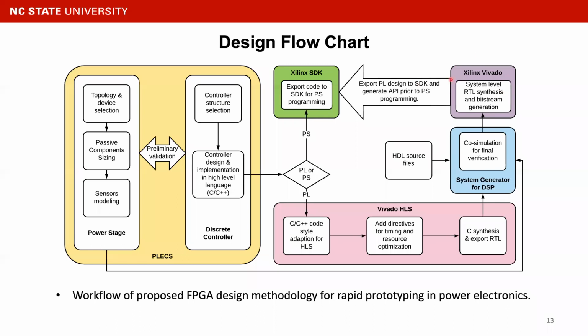After the bitstream generation, this concludes the development for the PL side. Then once the PL design is finalized, we can export that to the SDK environment to generate the proper API driver, and then we can start our PS design in the Xilinx SDK environment.